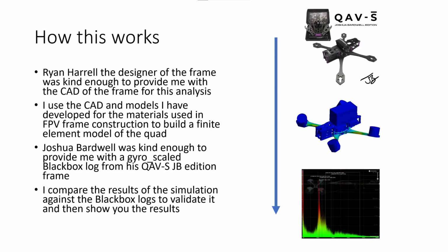I use this CAD as well as models that I've developed for the materials that are used in FPV frame construction, like carbon fiber, the material for the battery, the motors, all of these things. And I use all of that information to build a finite element model of the quadcopter in simulation space.